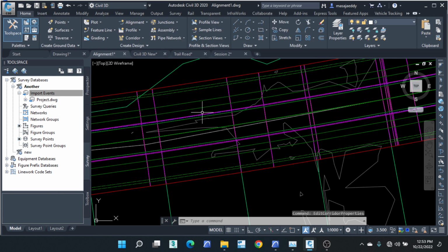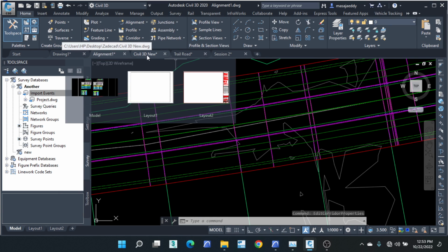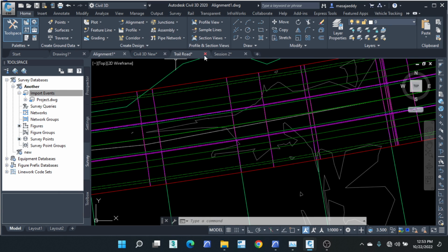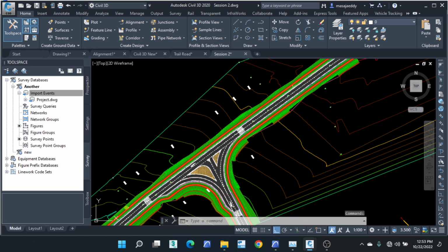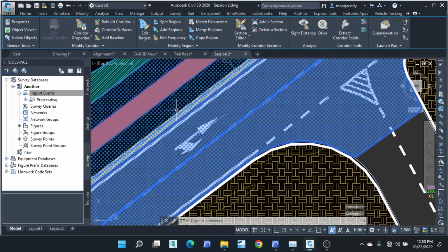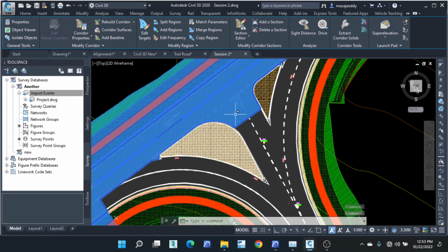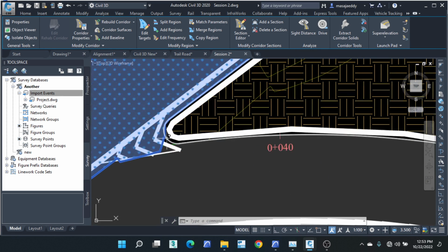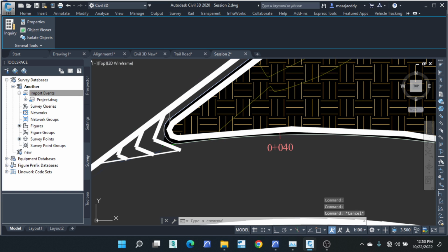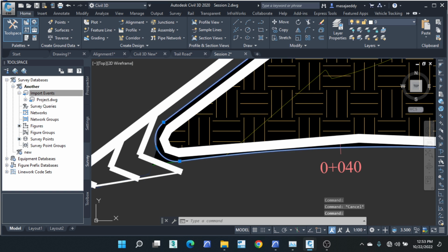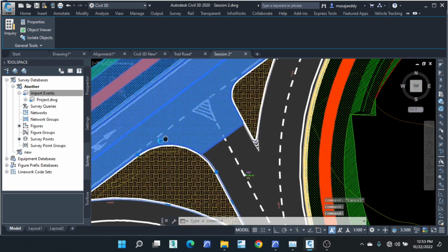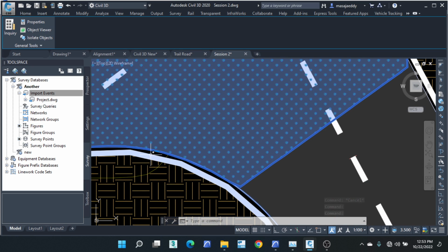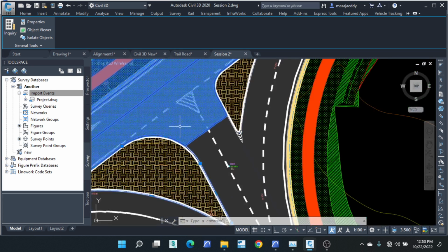So we have what they call targets. How targets work is that I can stretch, it's like stretching your assembly point to a certain variable. For example, I stretched this corridor. Instead of just running along this lane, it was stretched up to here. So I targeted a certain parameter here and also a certain parameter here. I targeted that corridor lane to reach up to this point. That's why it is curved along this feature line here. You get? You understand the variables? So that's what they call targeting.